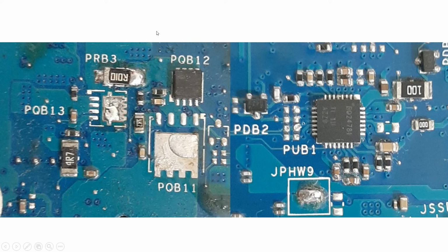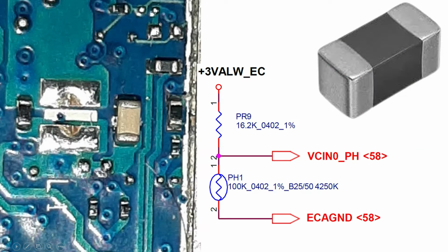This is the CLR. Here is one important piece of information I wanted to share with you. Here is the voltage divider, but one component is looking like a coil. Okay, the coil. Here, it is not a coil. Actually, this is a thermistor, a thermal resistor. This is an important point, please note it down. This is a thermal resistor. It looks like a coil, but it's not a coil.